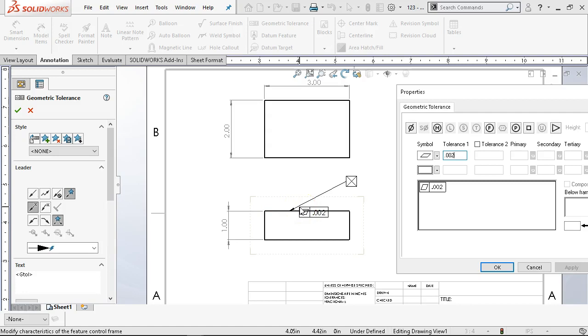All right, we'll try that again. Plus or minus 5, I could not have a flatness of 10 thousandths. I would be at the limits already of the dimensional tolerance. And so we want to be under that by at least half. So plus or minus 5, we could do 5, but if we were to take it to probably 2 thousandths, that may be a little more control than we need.